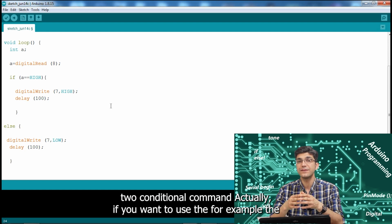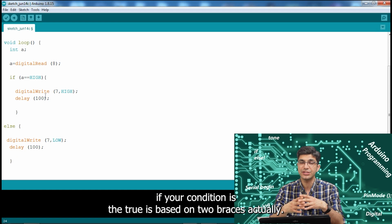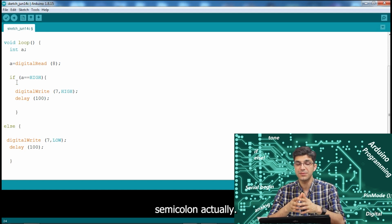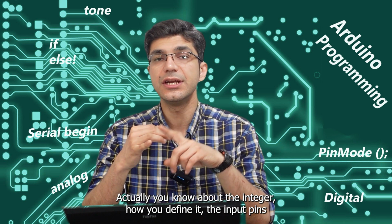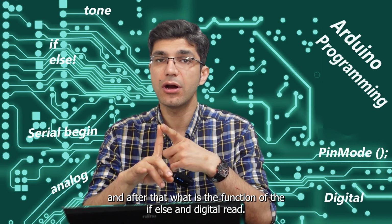If you want to use the if, the condition goes in the parentheses, and all of your commands, if your condition is true, go between two braces. All of the lines should have a semicolon. So please consider that in this code you now know about the integer, how you define it, the input pins, and the function of if, else, and digitalRead.